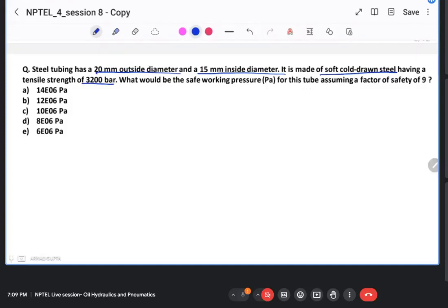So as you can understand from the question, this is an application of hydraulic conduits that allows the flow of the hydraulic fluid between different components. There are different considerations that should be taken care of while selecting a particular tubing. Number one is the frictional losses that can happen inside the tubing. So accordingly, you should be optimizing the length and diameter of the tube.